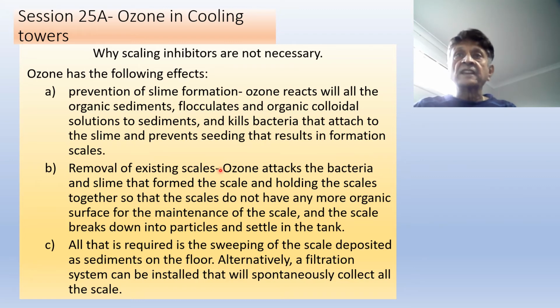Removal of existing scales. This is very important. Ozone attacks the bacteria and slime that form the scale, and the scales do not have any more skeletal surface for the maintenance of the scale, because the organic material or slime is a basis for the scale to cling together.